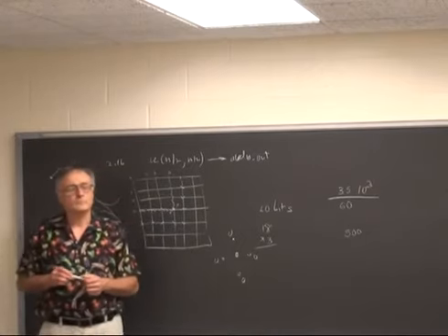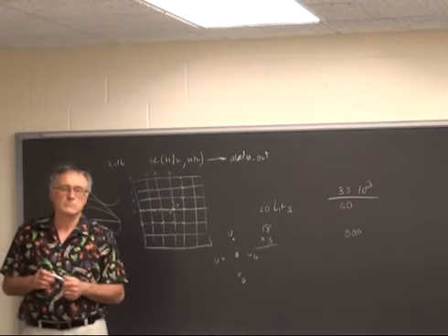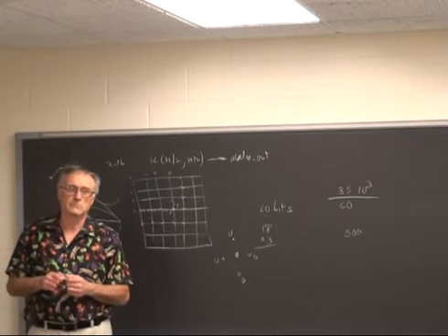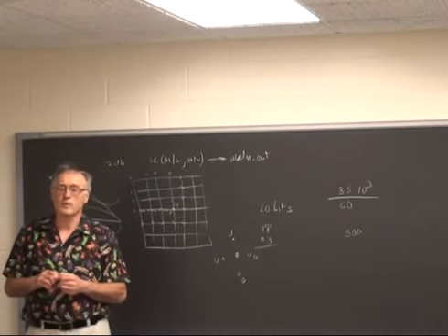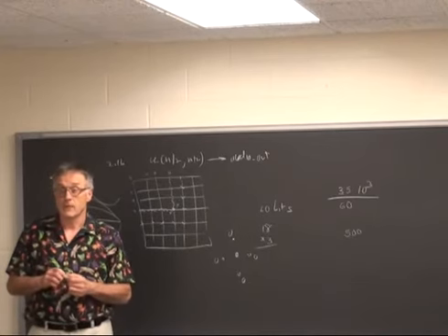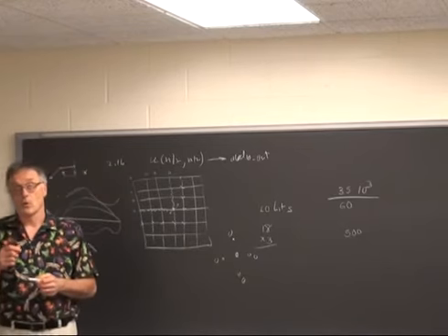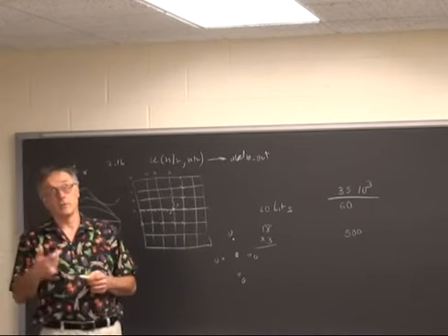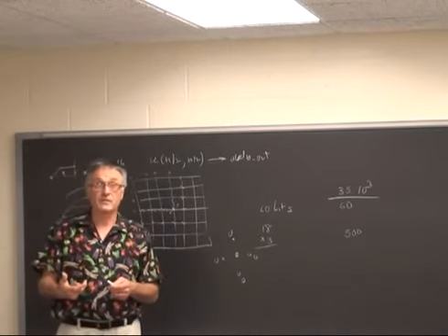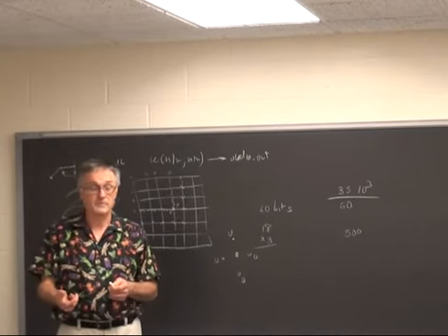What else? Anybody going to go for more than 18 bits precision? If you go for more than 18 bits, you have to ask then, are you going to use multipliers or not? If you're going to use multipliers, then the next obvious size to go to is 27 bits, because that's 3 times 9.